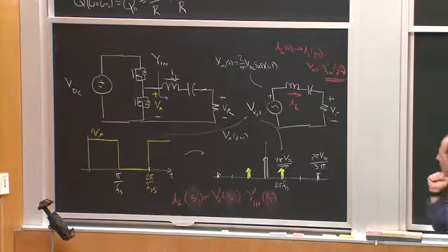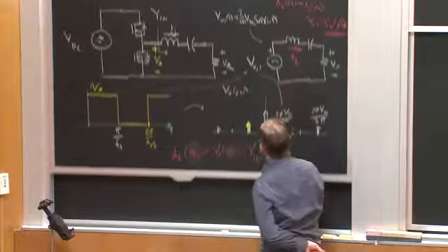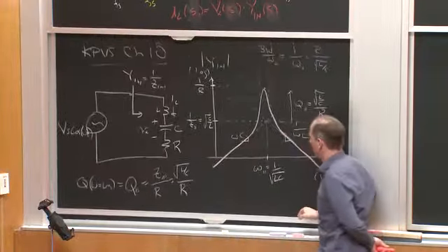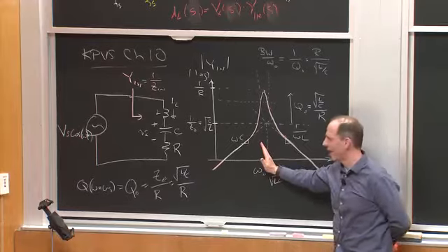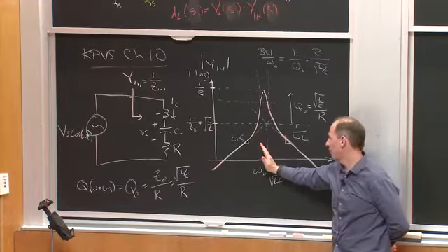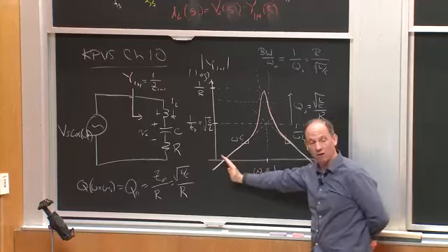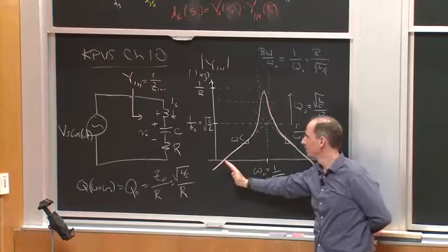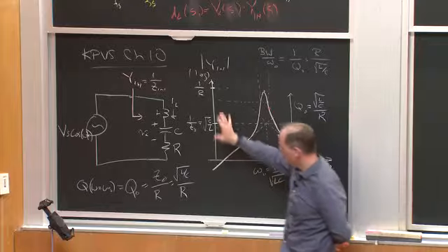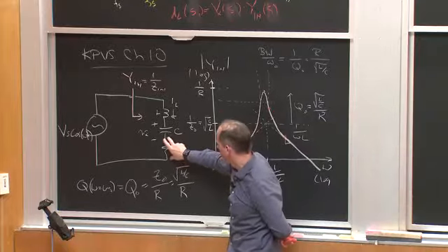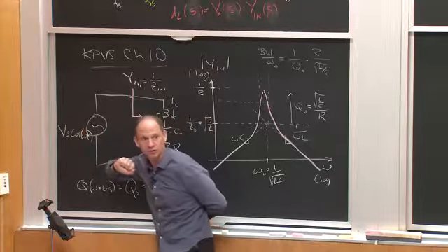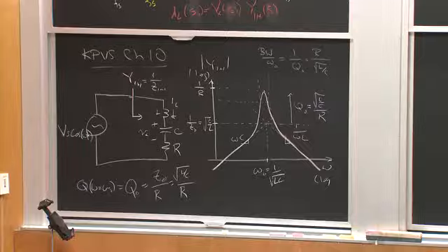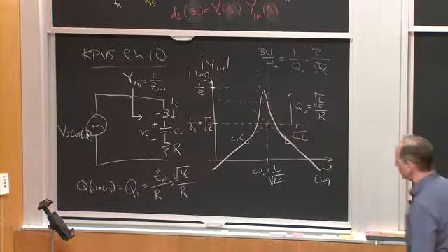We could modulate power by going in either direction off of resonance, right? According to this, if I put my switching frequency right here, I'd get maximum power for a given voltage, right? And if I go in either direction, the admittance goes down and I get less power. All right? And the maximum voltage I can apply with this particular network is the voltage across the resistor equal to the input voltage, or I should say the fundamental of the input voltage. Okay?